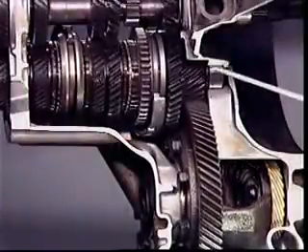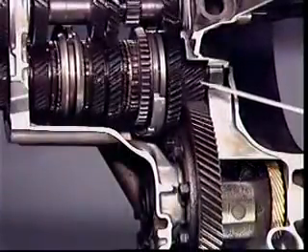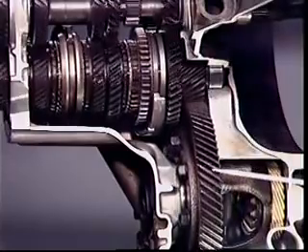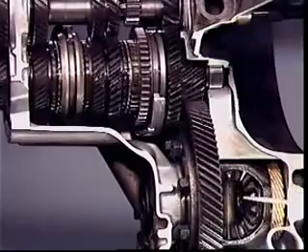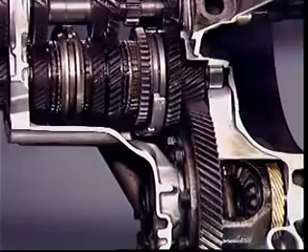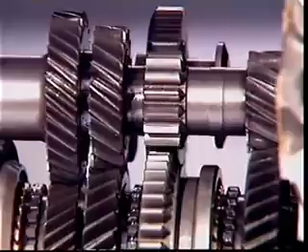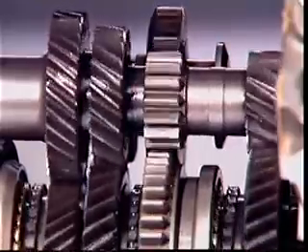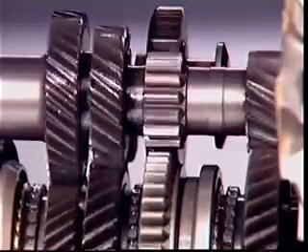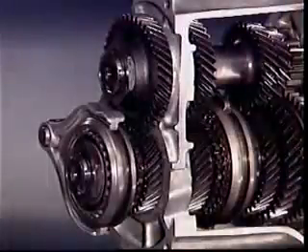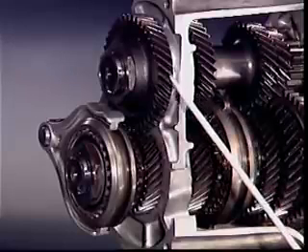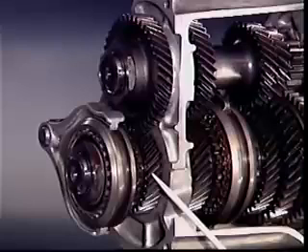A drive pinion gear fixed to the end of the secondary shaft is constantly in mesh with a final drive ring gear. The drive is transferred through these gears to the differential unit. A reverse idler transmits the drive from the primary to the secondary shaft when reverse is selected. A 5-speed transmission has an extra fixed gear on the primary shaft, meshed with a mating free gear on the secondary shaft.